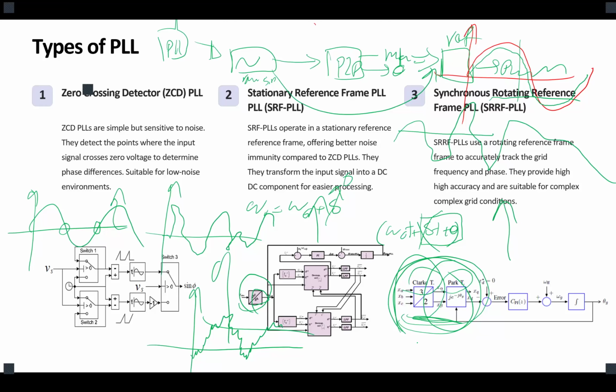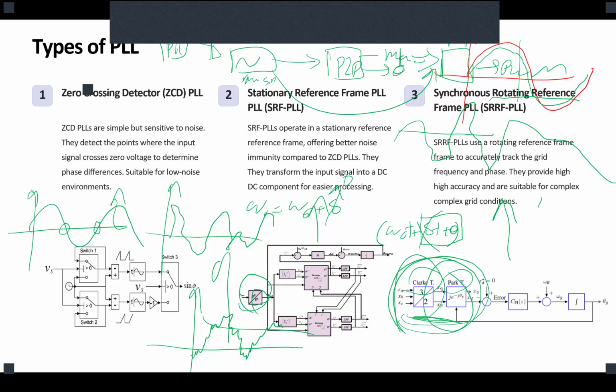I think I mentioned that at high frequency there is going to be a parasitic capacitance in a low pass filter that lets the ultra high frequency through. So a low pass filter doesn't just let the low frequency pass and cut the high frequency. After a certain point, because of radiation and parasitic capacitance, it goes up again. So ultra high frequency would pass through a low pass filter. Are we good? Any question? No? Okay.